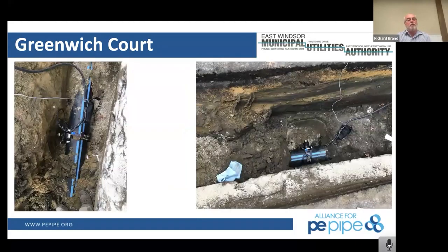Okay, on this picture here, this was Greenwich Court. Again, the reason why we do mostly open cut here is because we have high density housing. Our service lines are spaced approximately 20 to 30 feet apart. So even though we have to go in and tear up the road, that's why we decided to use open cut. Here you can see an electrofusion saddle being performed.